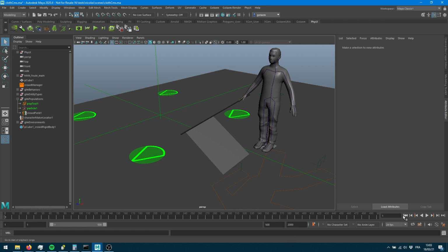And I kind of erased everything in my scene. So if I just run the simulation, nothing really happens because I just removed everything. You may have noticed that my arm is keyframed. That's something I really like to do, just to provide a dummy animation which shows what kind of motion and velocity I'd like to inject into my clothes. So while I'm setting it up, it's a good way to check that it reacts properly.